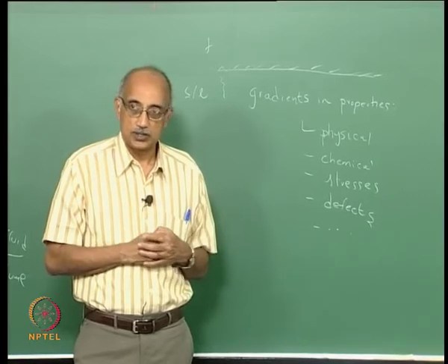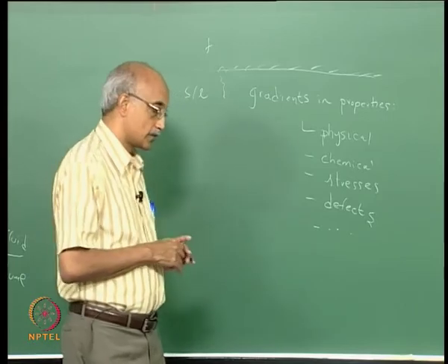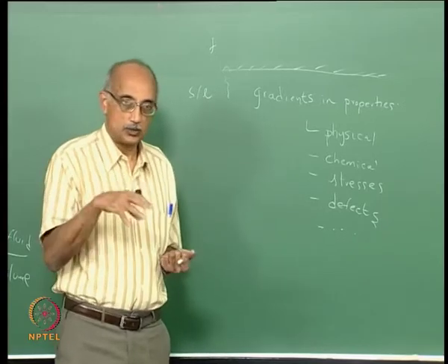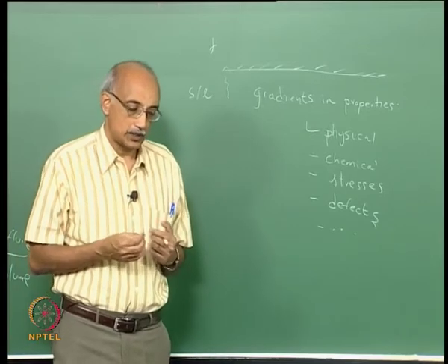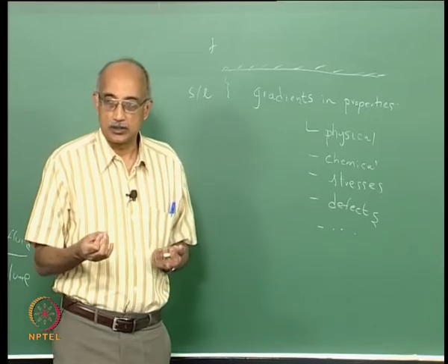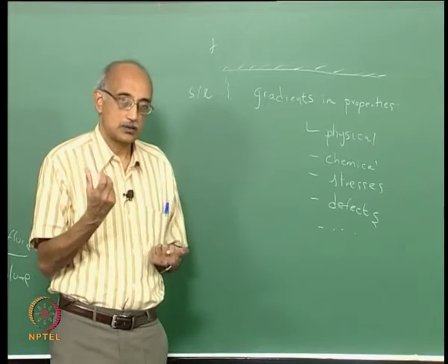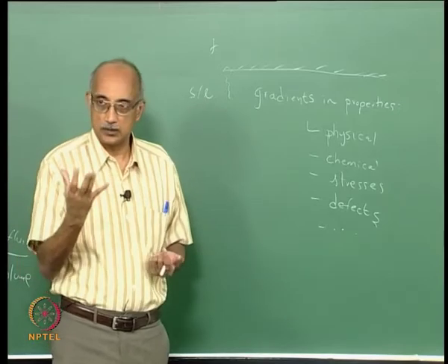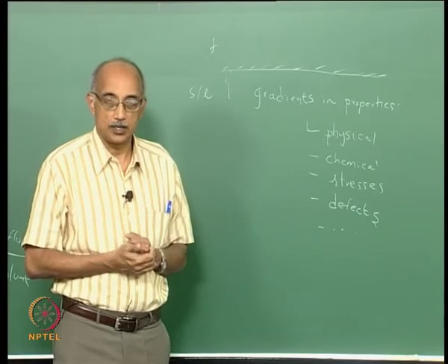Oxidation is a process that happens naturally, right? But you can also think about manufacturing processes where we are deliberately introducing a reactive gas to achieve a certain purpose. For example, when you have steels that have low carbon content and you want to increase the carbon content, there is a process called carburization that is used, which essentially takes carbon molecules and lets them diffuse into the steel surface in order to enrich the carbon in the steel alloy.